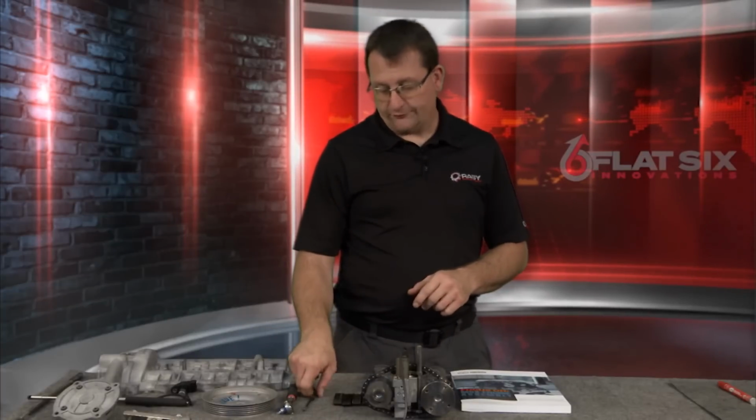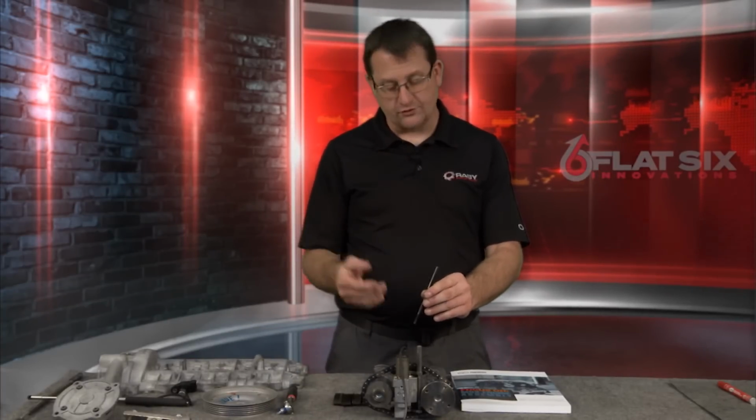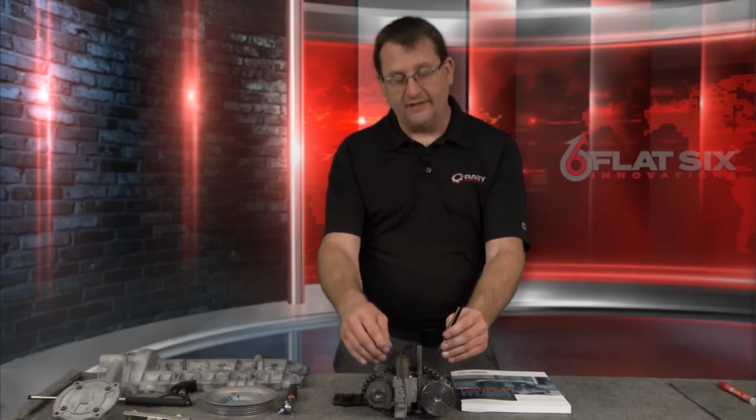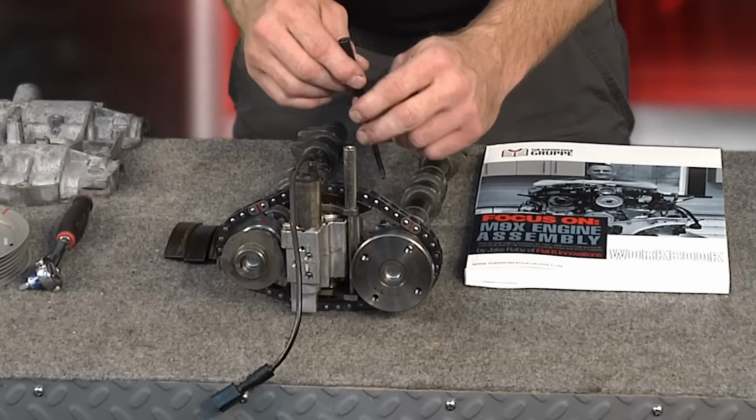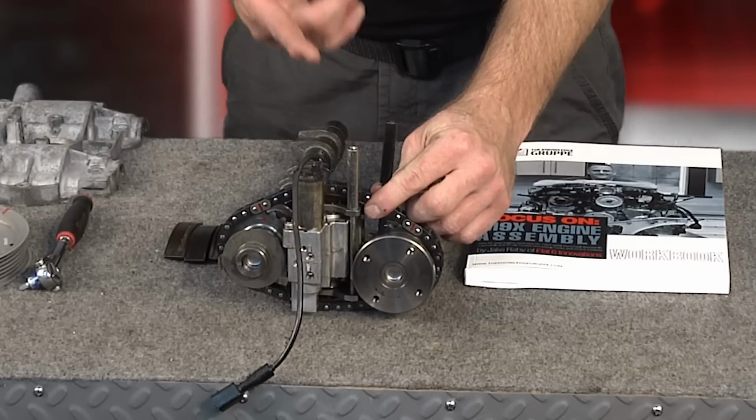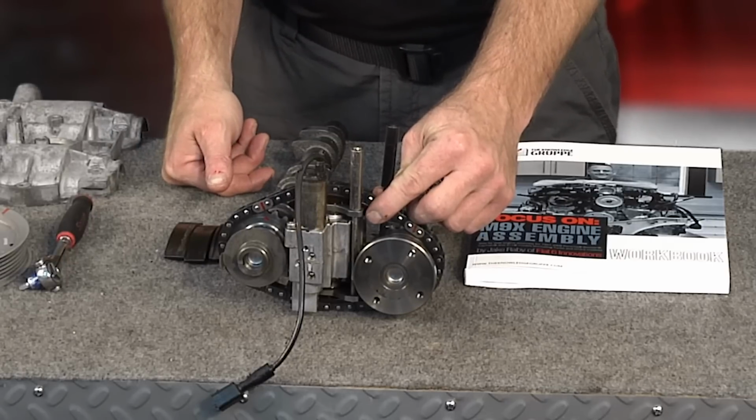So another tool that you're going to need is also available from BAUM or from Porsche, and it is made to collapse or compress the hydraulic chain adjuster unit to allow you to separate the simplex chain from the adjuster with the wear pads and all that sort of thing. One of these is gold, one of these is black. One has a right-hand thread, one has a left-hand thread. Some engines need a right, some engines need a left, based on the year model or if the chain adjuster unit has been replaced over the years or whatever the case may be.